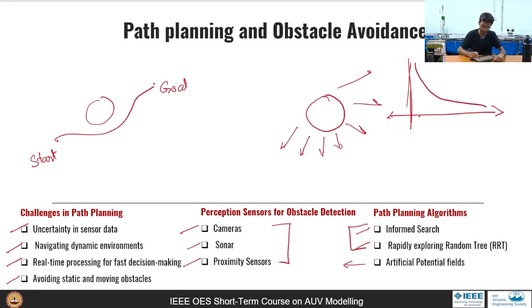As you can see, closer to the obstacle, the value of the field is much higher, and further away, the value is much lower. This indicates that as the robot gets closer and closer to the obstacle, the field aims to push it further away from it with higher magnitude. This allows the AUV to stay away from its obstacle as well as simultaneously try to maintain its course.